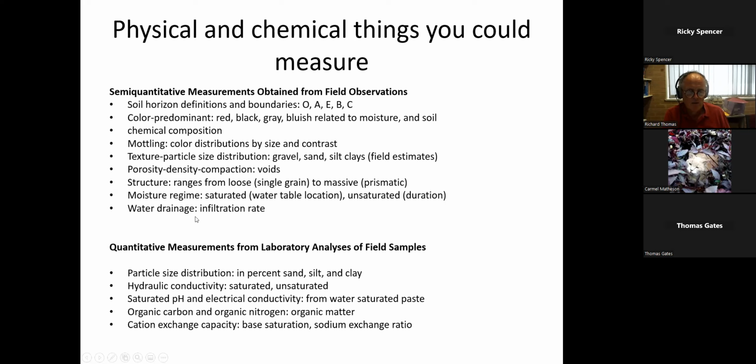And then that takes us into the water drainage and infiltration. The more porous the soil is, the lower the levels of drainage, and that will impact on other things. If somebody is applying inorganic nitrate as a fertilizer into a soil with very low holding capacity and very low porosity, that nitrate is pretty much going to go straight through the soil, literally like a dose of salts, and into the river system.